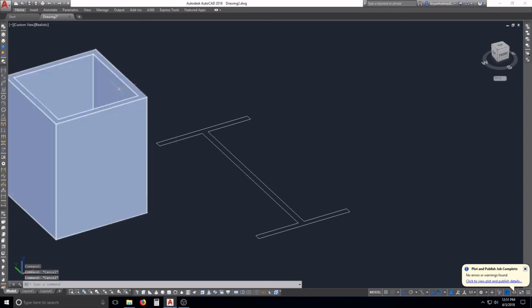If you're using solids, it actually can calculate volume and pressures and whatnot, whereas I don't think that capability is able to be used if you're using meshes. Meshes are primarily for just making something look pretty and changing stuff on the fly, from what I understand. Now please correct me if I'm wrong. That's my understanding of it.